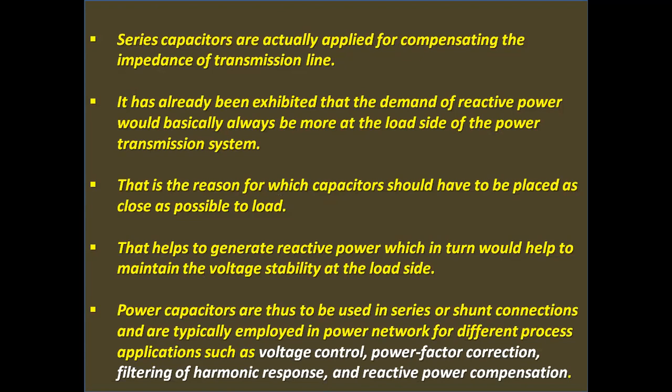That is the reason for which capacitors should have to be placed as close as possible to load side. That helps to generate reactive power, which in turn would help to maintain the voltage stability at the load side.